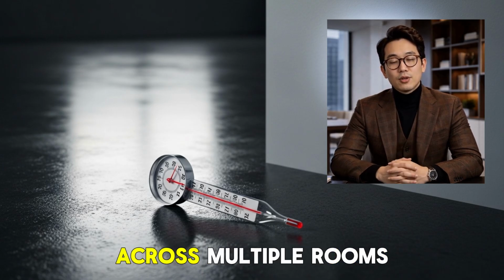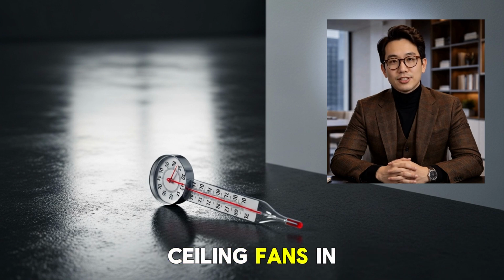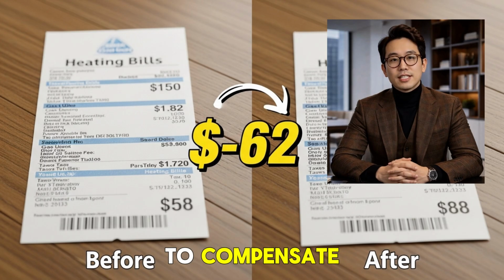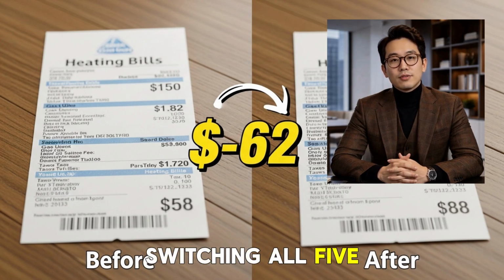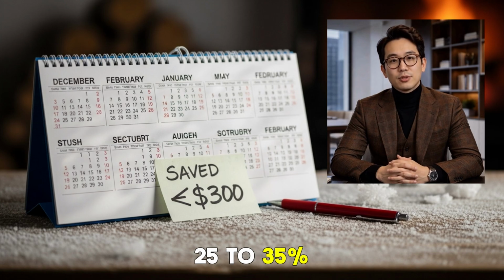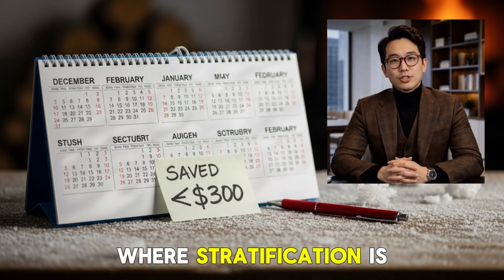The effect compounds across multiple rooms. A home with ceiling fans in living room, dining room, and 3 bedrooms has 5 fans total. If all 5 run in wrong direction during winter, the heating penalty multiplies. Each fan pushes cold air down and warm air up, forcing the furnace to compensate across the entire house. Switching all 5 to correct winter rotation reduces whole house heating load by 25 to 35% in homes with high ceilings where stratification is most severe.